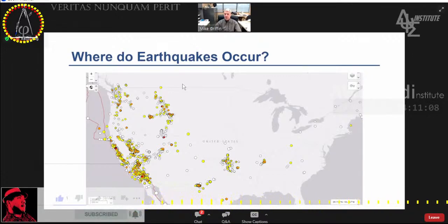We can also have intraplate earthquakes. Look at Oklahoma, for instance. That is primarily subjected to human activity, or fracking, where we're seeing an increase in earthquakes in those locations. They're generally not as large as we'll see on the plate boundaries, but nevertheless can be quite large. New Madrid, just to the right, in southeast Missouri and northeast Arkansas, is where we've got the New Madrid seismic zone, and that has historically been able to generate very large earthquakes.